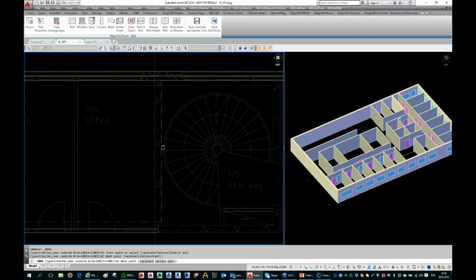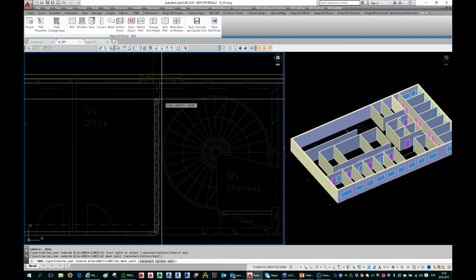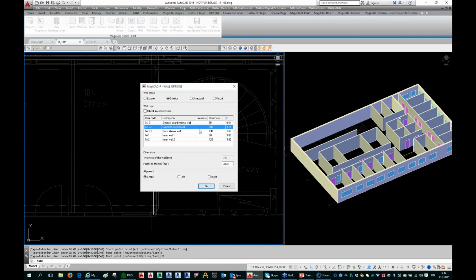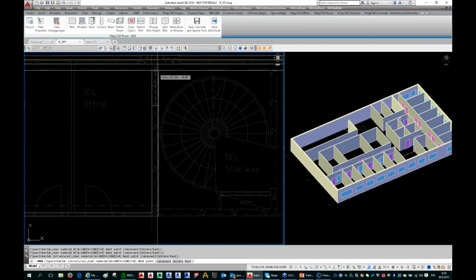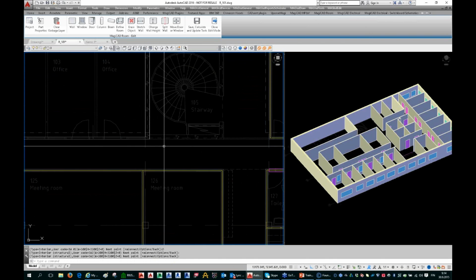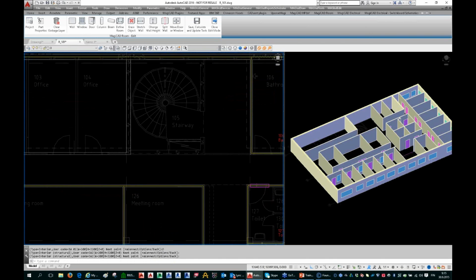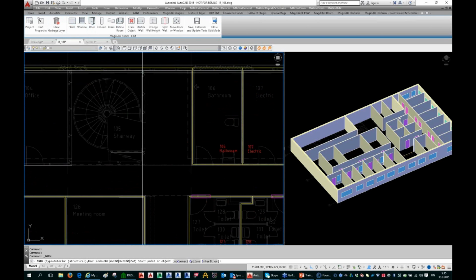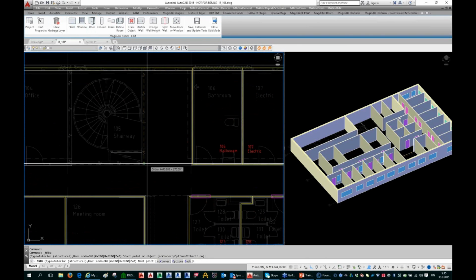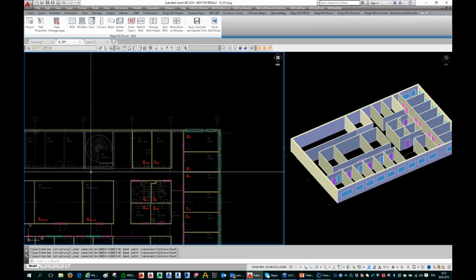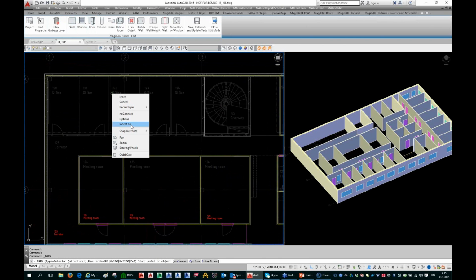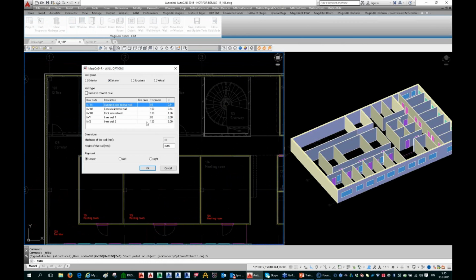And here I have a thicker wall, a structural wall. I will change my wall, right click, options, structural. I take this and I draw and connect to there. And when I want to continue, I just take the wall again, and then I connect to there, and I will draw my wall to there. And then I will connect my interior walls